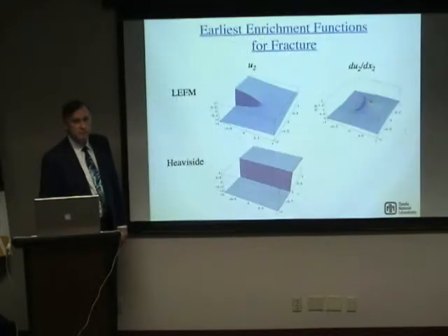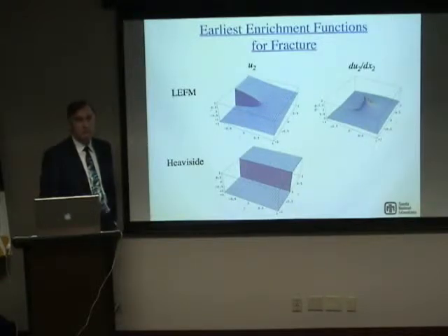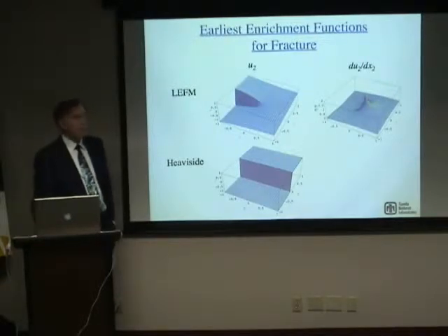You have to know where to enrich, right? Yes, yes. If you enrich in areas where it's not needed, you get a zero coefficient for enrichment or a very small coefficient. There are a few different problems. If you enrich too far away and your function is becoming almost constant in those regions, you can also have issues with regard to singularity in the matrix as well. But yes, one of the things you want to do is to enrich where it's going to help you in terms of the gradients and not in other places. All around the crack? Yeah, so we'll do that all around the crack.